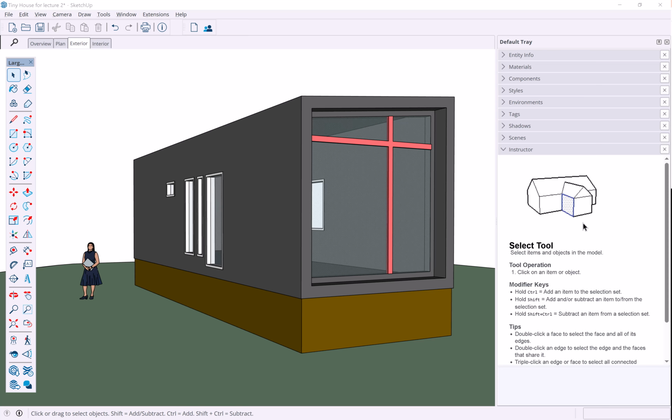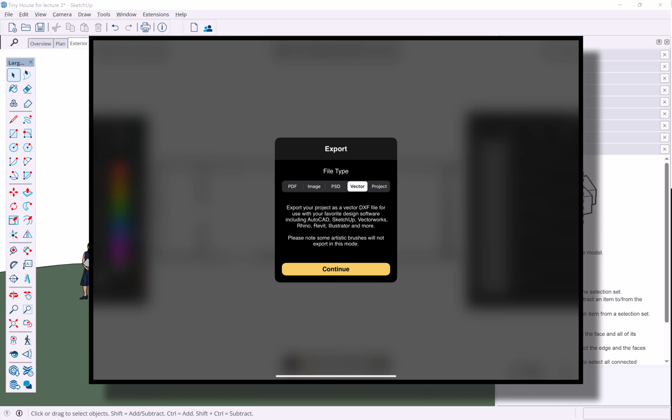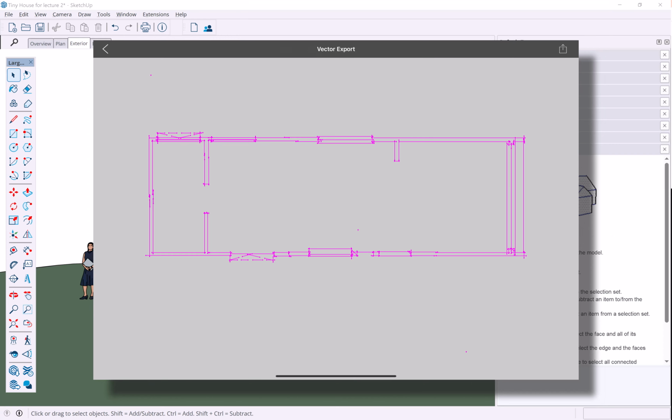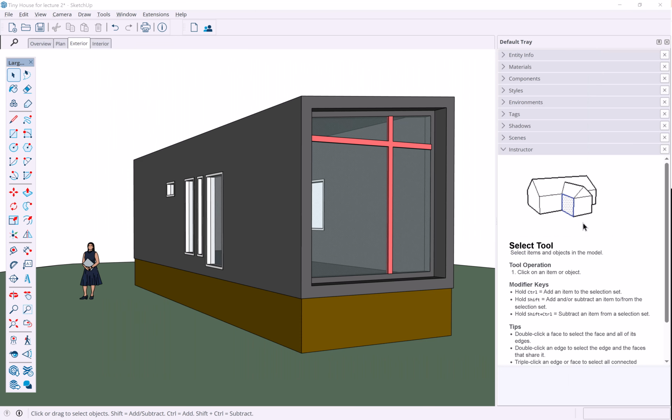And because we sketched this using Morpholio Trace, there is an option in Trace to share your document as a vector-based file. And it's pretty easy. You just tap the share button and choose vector-based. Make sure to turn off all the other junk. We don't need any of the colors or any of that sort of thing. Once you've exported it, go to SketchUp and you can import it.